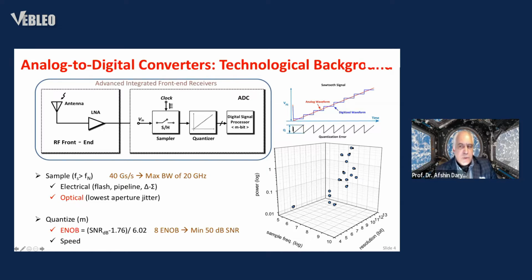Naturally, we want to minimize the quantization error to have the signal in digital format as close as possible to the analog information. And if you're looking at the information that is going to be sampled, the least sampling rate that you have is the Nyquist sampling, and in many applications, such as Delta Sigma ADCs, you want to have sampling that is faster than the Nyquist.